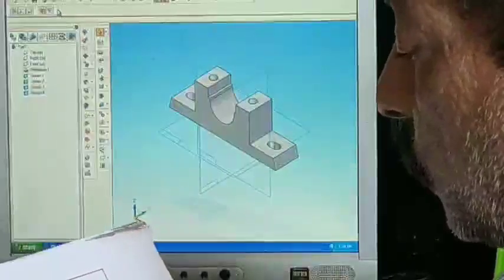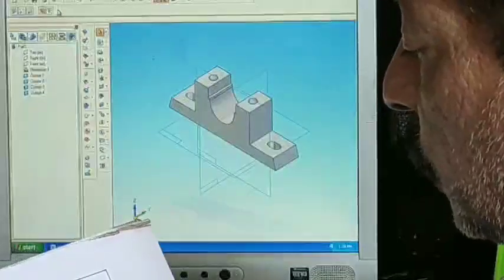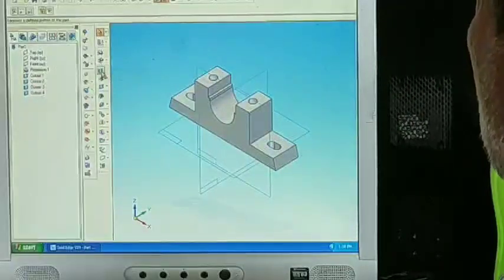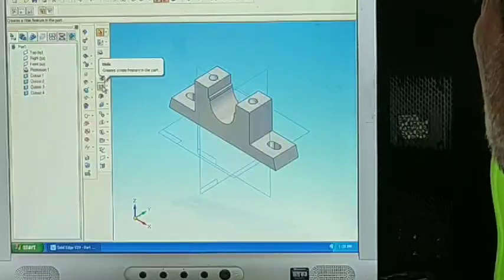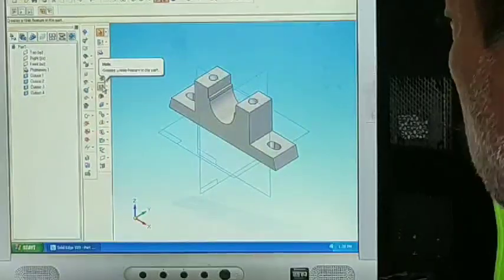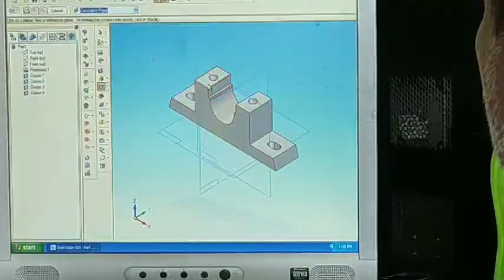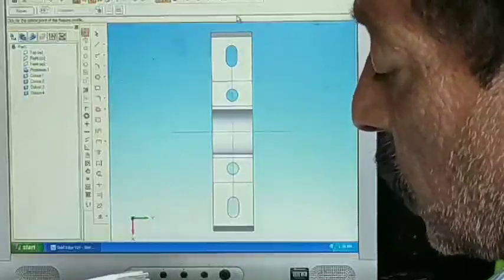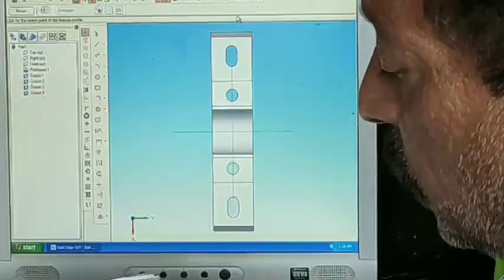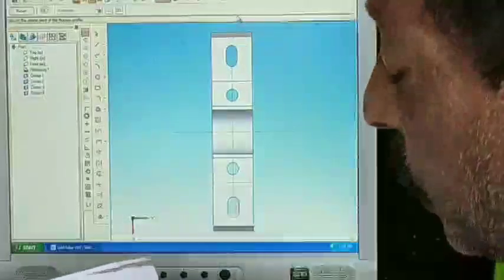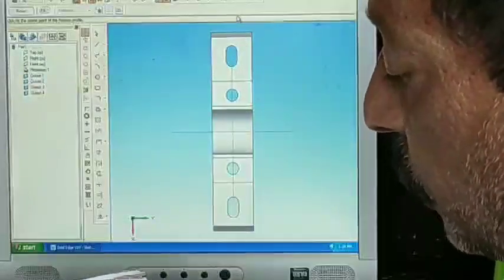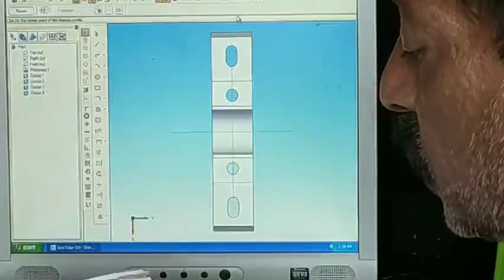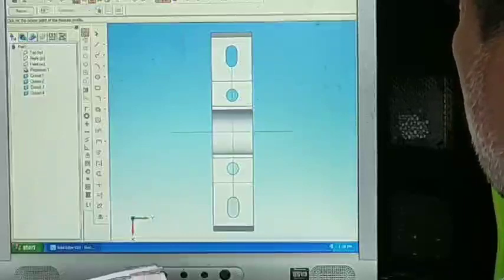So now there is a V bottom section here, that is V shaped hole. So for that one, go to revolved cutout, hole option here. See here, the first distance is 12 mm. Next distance, that is depth, is 3 mm. 12 plus 3, 15 mm. Next the radius is 19 mm. 15 plus 19, 34 mm. So depth of hole is 6 mm. Totally it is 40 mm.